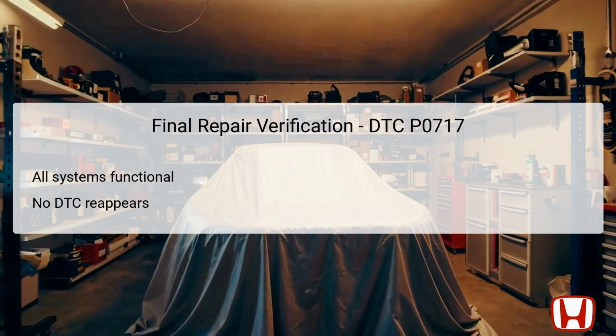To confirm successful repairs after addressing DTC P0717, a thorough verification process is essential. First, ensure that all systems are functioning properly by inspecting the performance of the CVT under various driving conditions. After conducting the necessary repairs, it is crucial to clear any DTCs and monitor for the reoccurrence of the P0717 code.